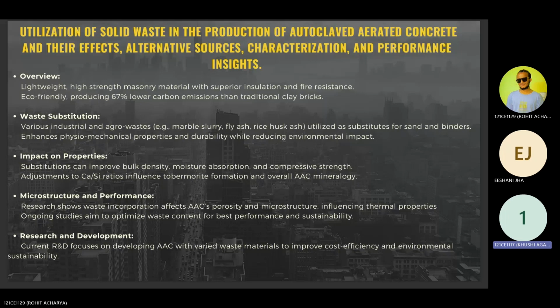Now we shall become acquainted with the utilization of solid wastes in autoclaved aerated concrete. We shall go through its effects, automated process, characterization, and performance insights. It basically involves the creation of lightweight, high strength masonry material with exceptional insulation and fire resistance properties. It is environmentally friendly, emitting 67% fewer carbon emissions compared to traditional clay bricks.